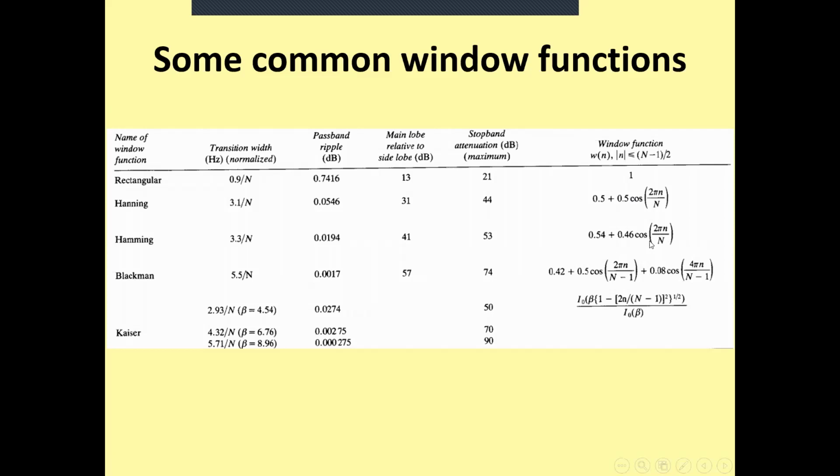So at the beginning, we have picked up the equation of ideal impulse response. In the second step, we are going to select the suitable window type and determine the N capital. Then the next step will be just substituting the values and calculating the coefficients of the desired filter.